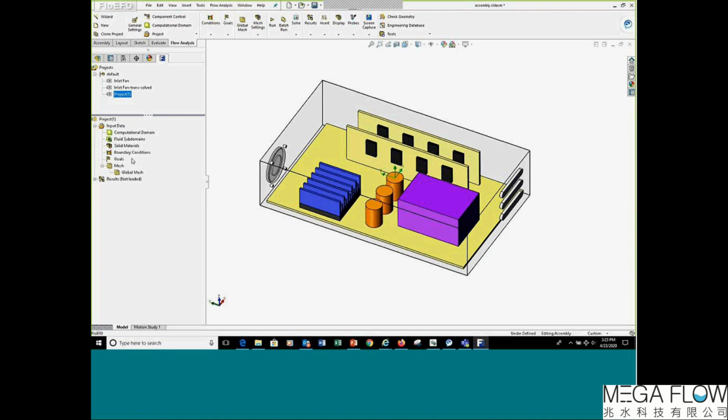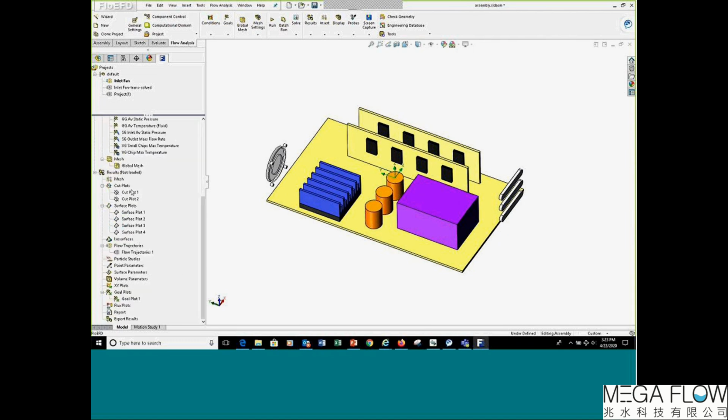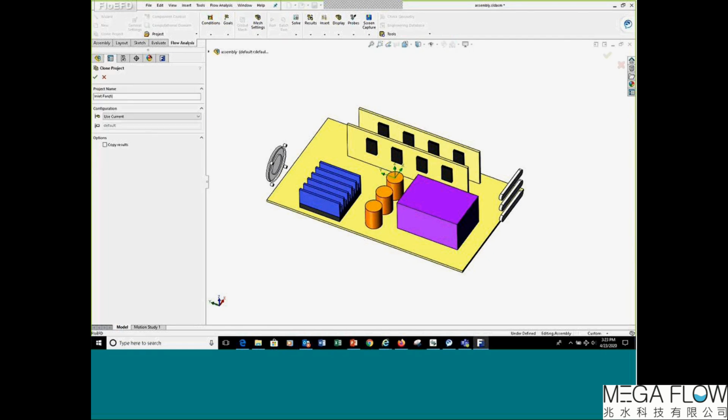So it's not like I'm done and I can just go ahead and hit the run button. I still have to set the model up. That's why, let's go back and activate our steady state. This is why it makes more sense to do this as a steady state, set up all your conditions, even do your post-processing. Then let's clone this. Let's right-click on that steady state project, hit the clone button, call this one Transient 1, for instance, say OK.